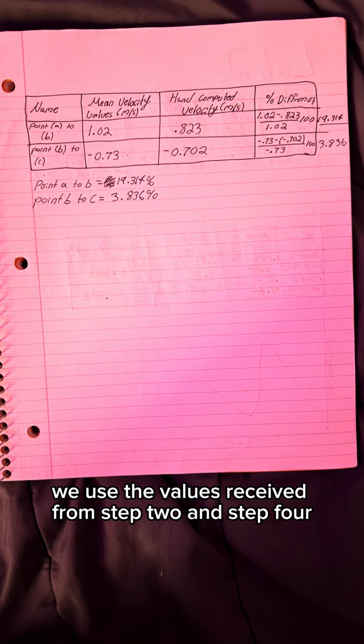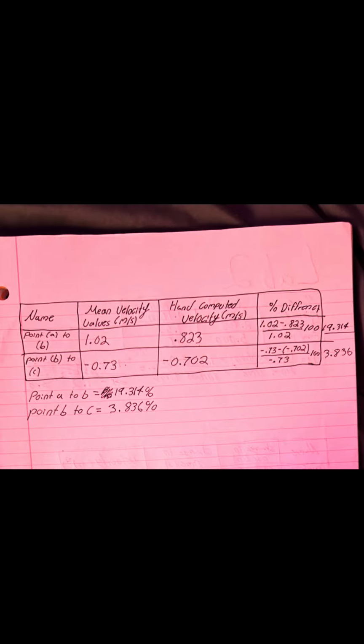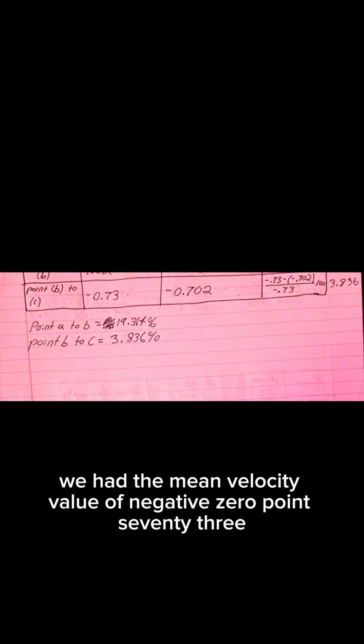Lastly, for step 5, we used the values received from step 2 and step 4 to find our percent difference. From point A to point B, our mean velocity value was 1.02 meters per second, and the hand computed velocity came out to 0.823 meters per second. Using the percent difference equation, we put 1.02 minus 0.823 over 1.02 times 100, which gave us a total of 19.314%.